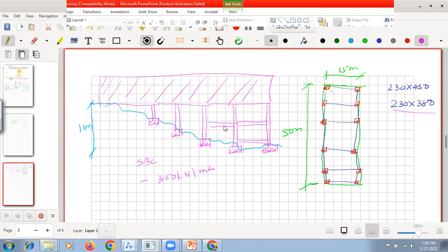Secondly, this was a ground structure. Okay, so as it was a ground structure, they had given some brick masonry around the periphery, and they had suggested the backfilling inside, as generally we give 2 feet or 3 feet, 0.6 or something.